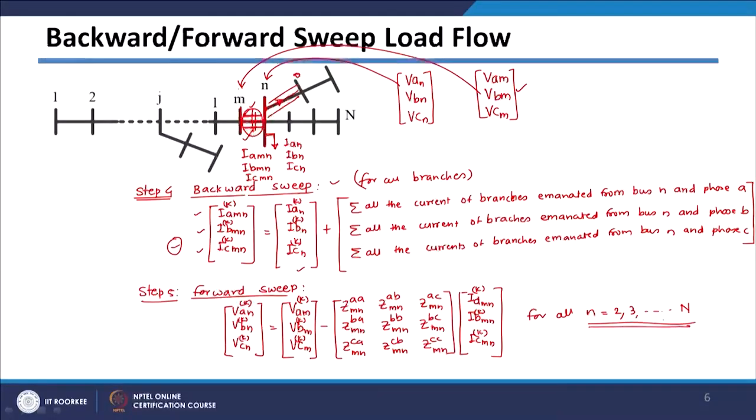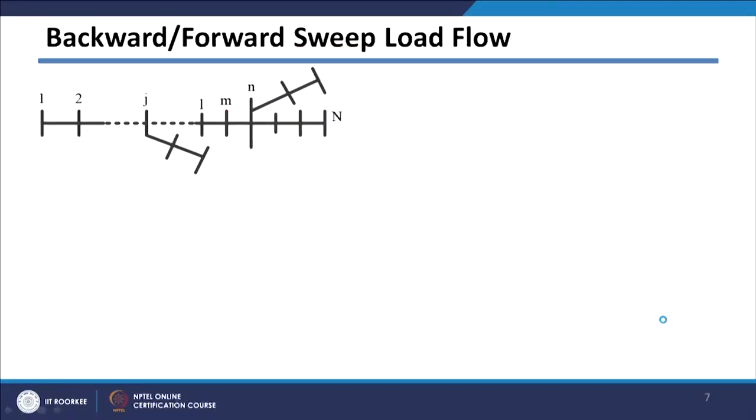So, this is how we get all the nodal voltages, and then we have seen that step number 6 is to get the errors of the voltages. Now, here there will be 3 errors. So, error of the voltages of jth bus in kth iteration will be equal to max of.